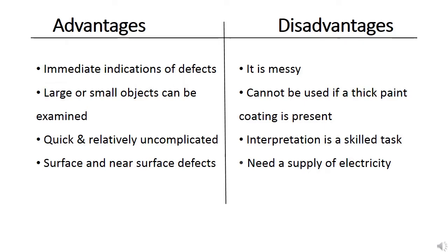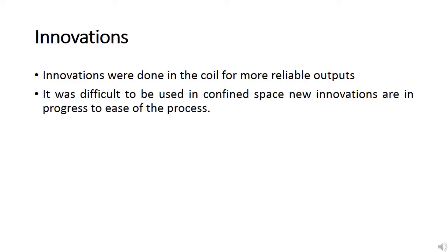Advantages: immediate indications, objects can be examined, uncomplicated, surface and near-surface defects. Disadvantages: it is messy, cannot be used if a thick paint coating is present, interpretation is a skilled task, and it needs a supply of electricity.